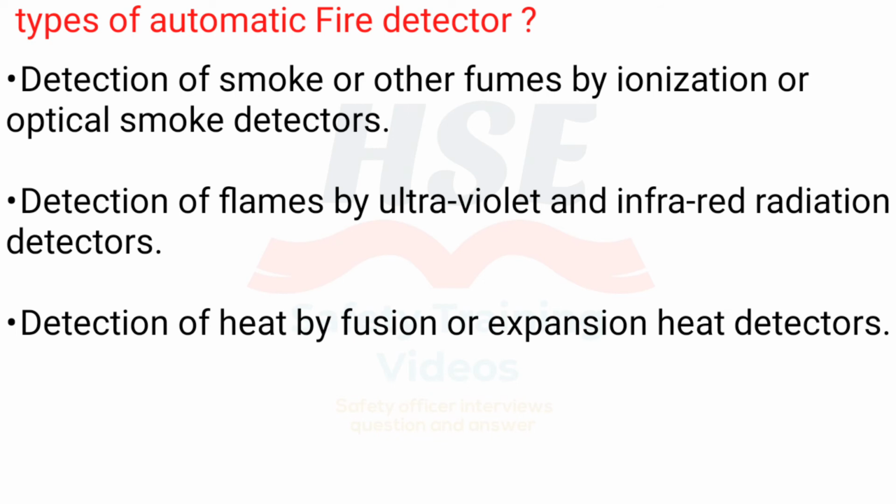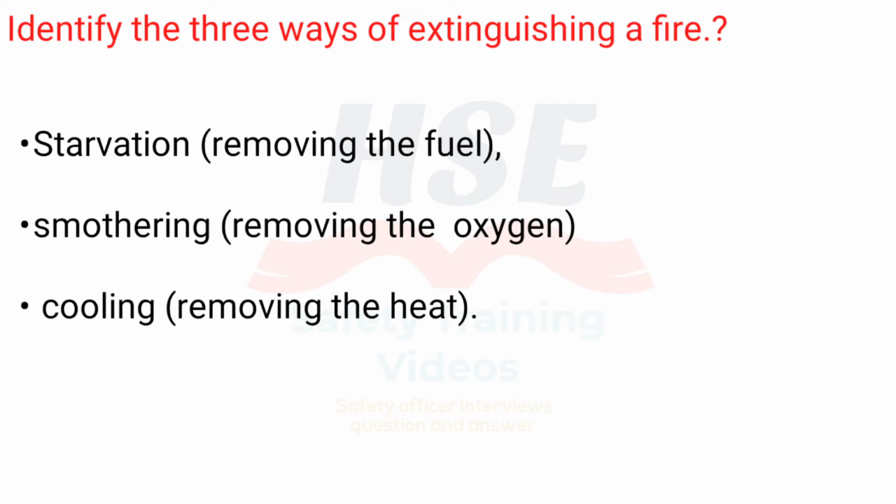Types of automatic fire detector. Detection of smoke or other fumes by ionization or optical smoke detectors. Detection of flames by ultraviolet and infrared radiation detectors. Detection of heat by fusion or expansion heat detectors.